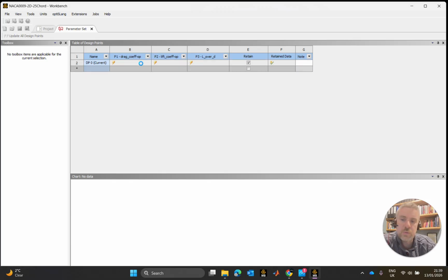all my values. This would have been populated, but I can now add in another design point, and if I had any input values, which I will create in the next video from either named expressions or field functions, I can alter them here, including velocity, angle of attack, whatever I want, run the calculation out here, and that saves me having to go into Fluent, and it will output for me my values. Okay, so for the mesh independence, we'll also look to populate this with maybe mesh sizing or spacings and whatnot.